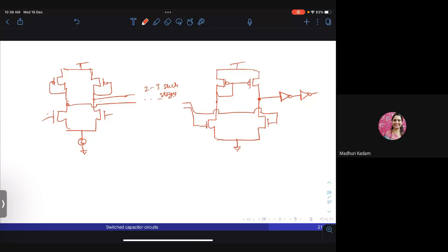Okay, so by using a cascade of such amplifiers, you can easily convert a small differential input to a proper digital decision, which is either +1 or -1. All that is important now is that this amplifier chain should have very low offset. So you don't want offset to affect the transfer of basically the decision from +1 to -1.